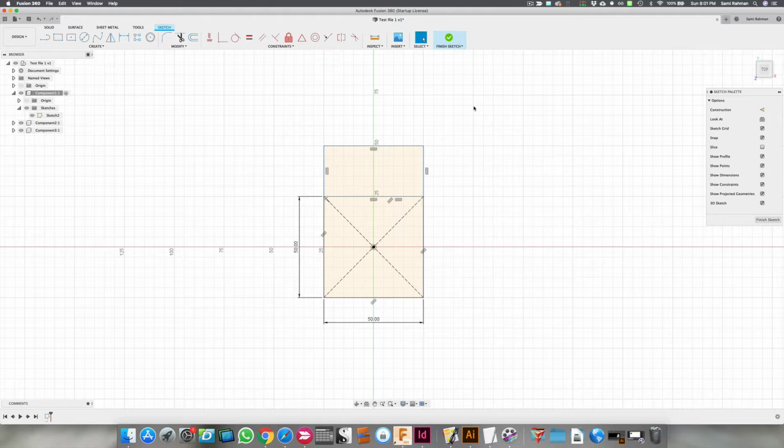If you start from the right-hand side and go left, when you do your selection, anything that touches that box is going to get selected. So if I want to get both that box and that box, I can just come in here real quickly and do that. But if I were to do the same thing by clicking and dragging from the left-hand side to the right, let me just do that. I may only get 1 point, because the point is the thing.